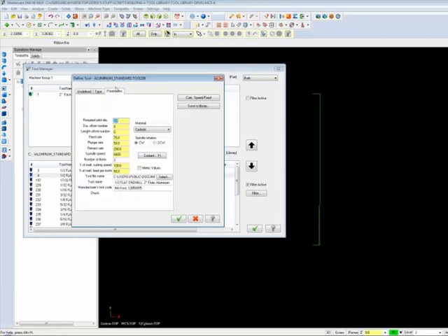Since we weren't supplied any feeds and speeds, we'll have to use our best judgment. Let's set a feed rate of 50 inches a minute, a plunge rate of 25 inches a minute, a retract rate of 25 inches a minute, and a spindle speed of 5,000 RPM. The tool has 3 flutes, it's made from TiN-coated carbide, and it uses coolant.